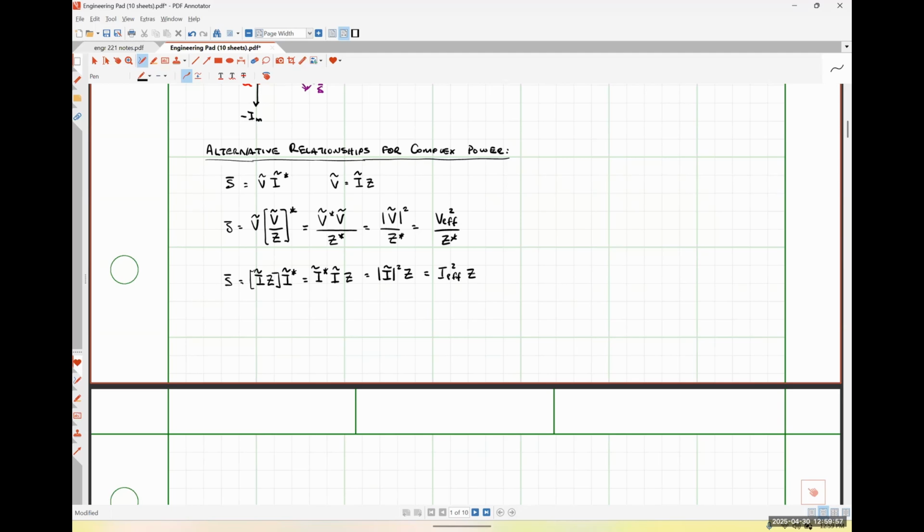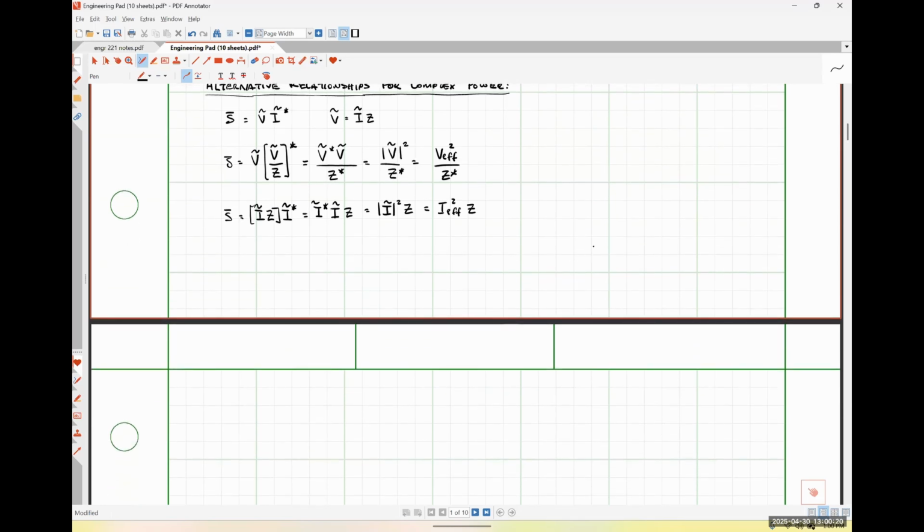So we have these two generic relationships that are valid for literally any impedance whatsoever. But I want to take these now and use them to determine the complex power in terms of both current and voltage for resistors, capacitors, and inductors, so that we can kind of see what roles they play in AC systems. So for a resistance, or for a resistor, and just to be clear here, that means that my resistance is positive and my reactance is exactly equal to 0.